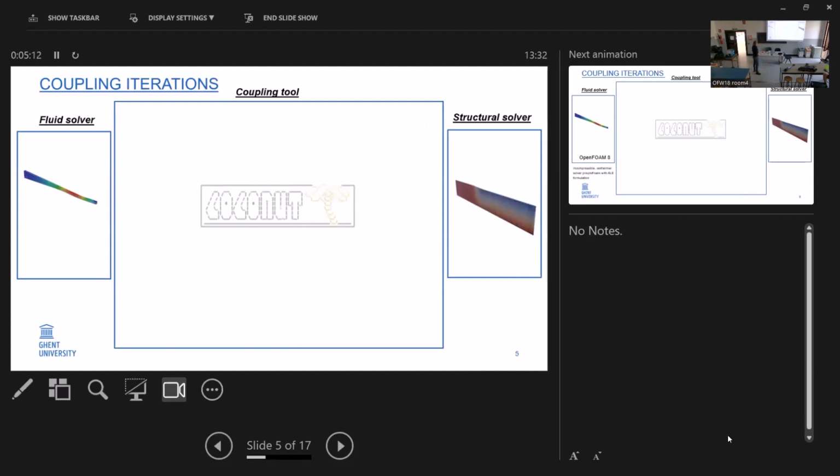All right. So we have here the fluid-structure interaction. What does that mean? It is made of three components: a fluid solver, a structural solver, and a coupling component. The fluid solver solves a thin film, a compressible isothermal thin film, with an arbitrary Lagrangian-Eulerian formulation.